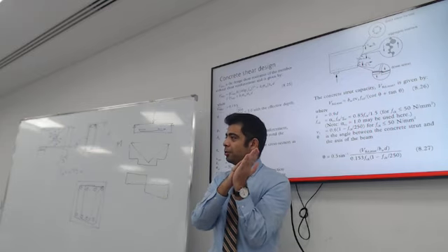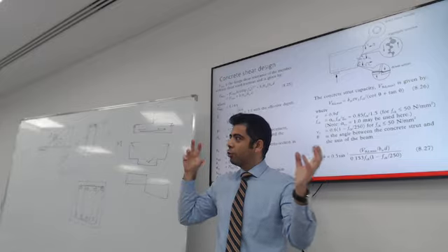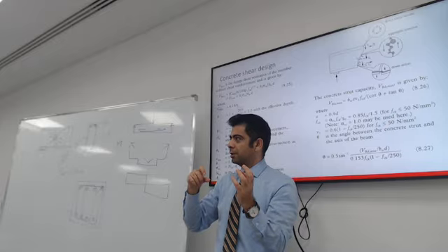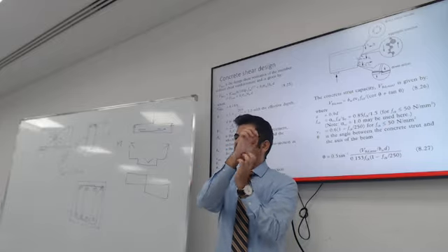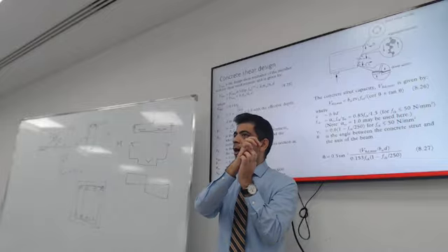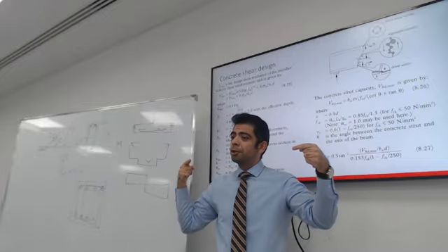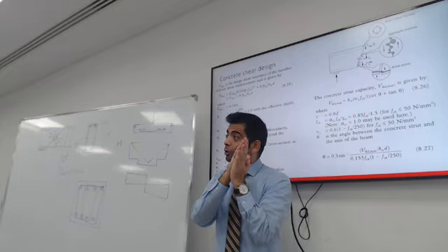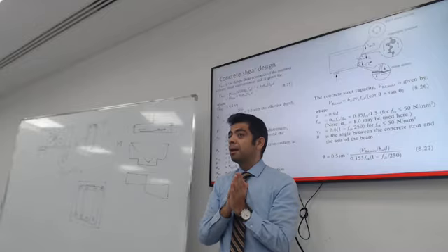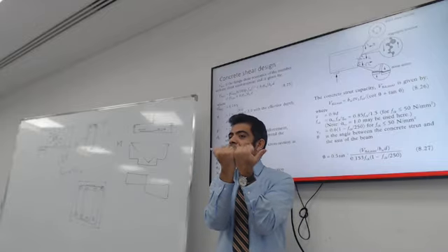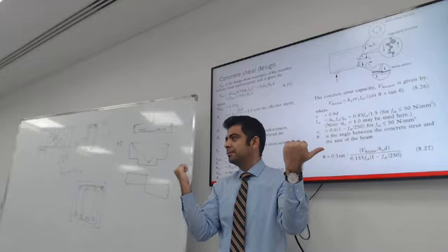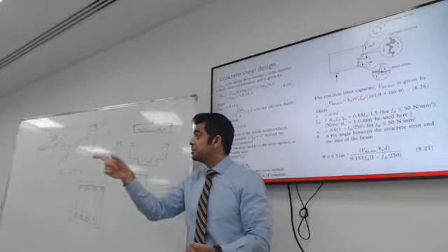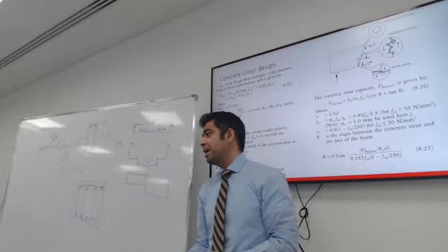You know how friction works? It's the normal force times the coefficient of friction. The coefficient of friction is taken into account with the aggregate interlock. If there is compression force, it makes it more difficult for shear to slide. Can you guess what will happen if this beam has a tension on it? It's easier to break. It will reduce the shear capacity.